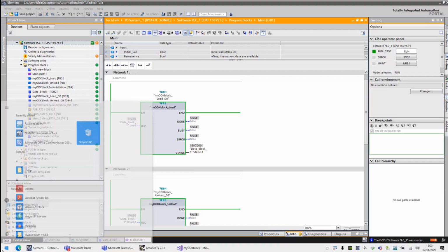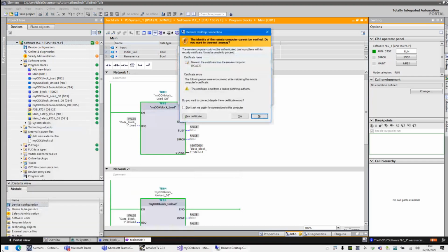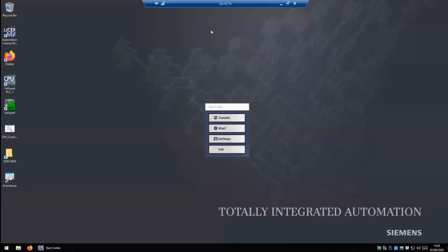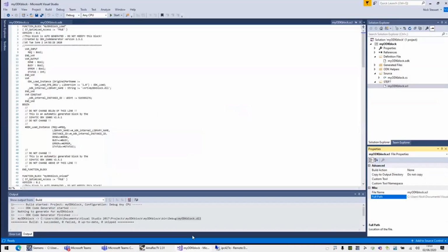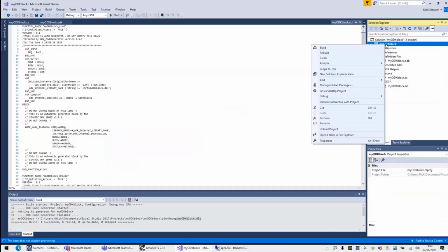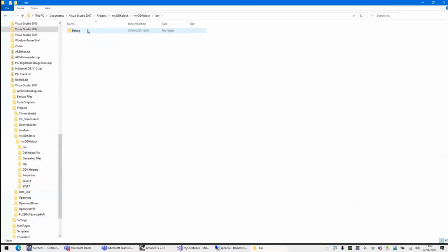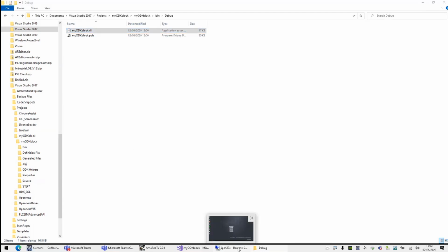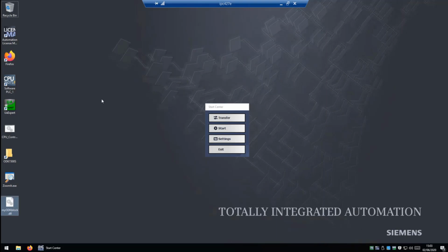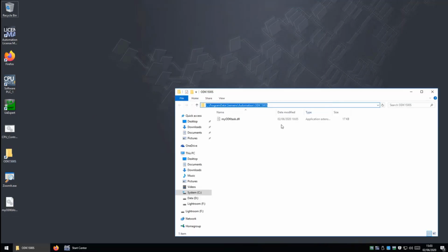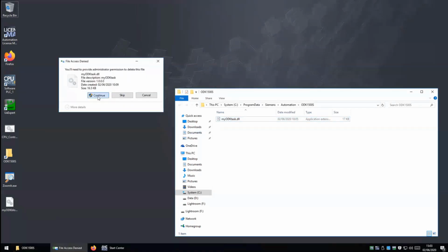And we'll now quickly jump onto the IPC again for the purpose of deploying our ODK function. So if I go back into my Visual Studio, if I right click and go open folder in File Explorer, I should be able to poke around and find my DLL. So I'm just going to copy that onto the clipboard using remote desktop this time, back into the IPC, paste it onto the desktop. I've got a shortcut to this directory. We'll remove that because we don't need it anymore.